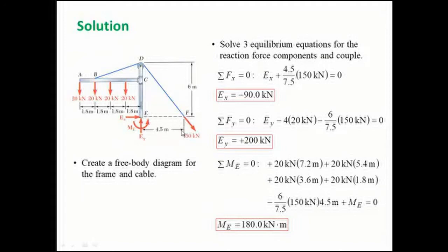The vertical force will produce a moment. The perpendicular distance is 4.5. That is given here. The vertical component into perpendicular distance, and it is producing clockwise moment. So finally I am able to get Me as positive. So my assumption is right.